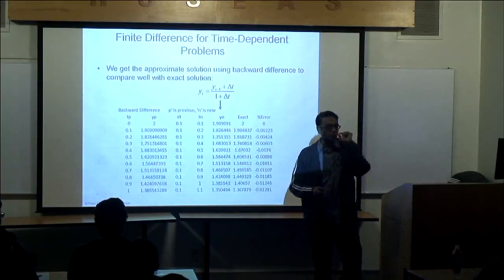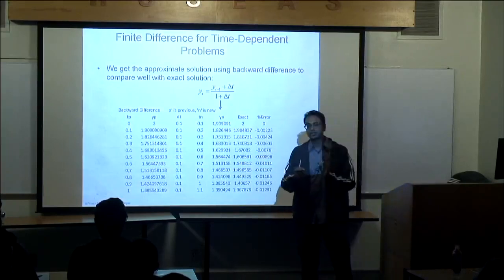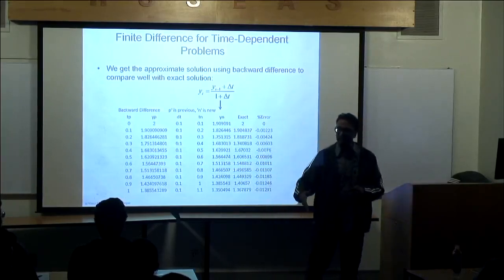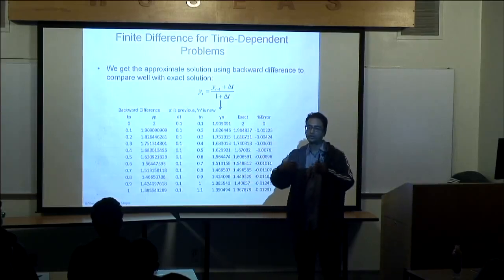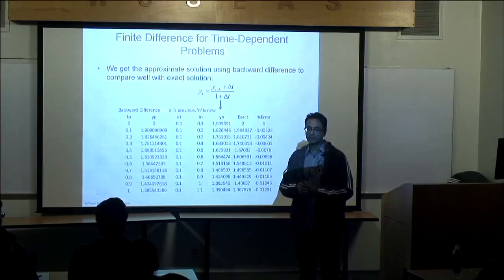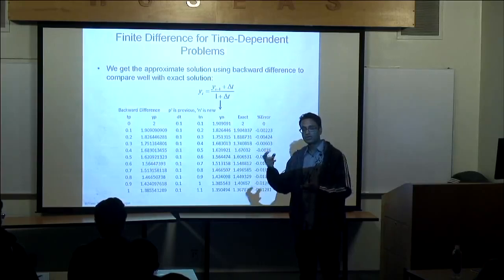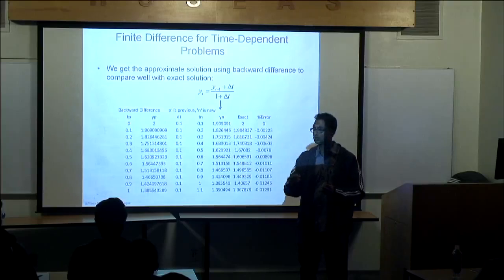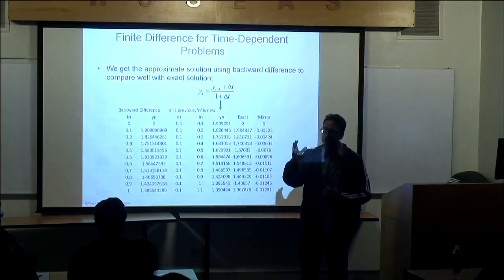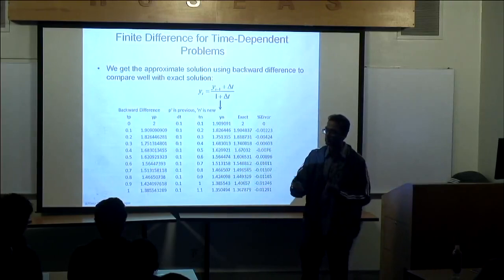Likewise, you can have problems where things are happening in a fraction of a second, like an impact dynamic event or a hail impacting a composite. And I want to know how the composite structure responds, which is a good application for aircraft structures, right? In that application, I want to know what kind of damage the hail is going to do to the composite. There, I probably want to reduce the time step to scales even less than 0.1 seconds because everything's happening maybe in microseconds, right?